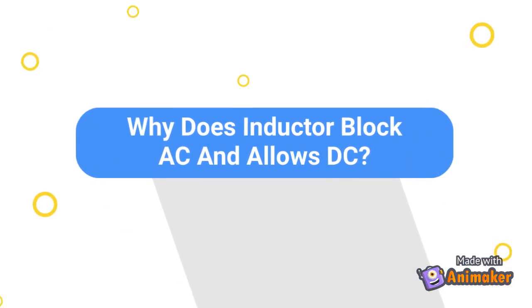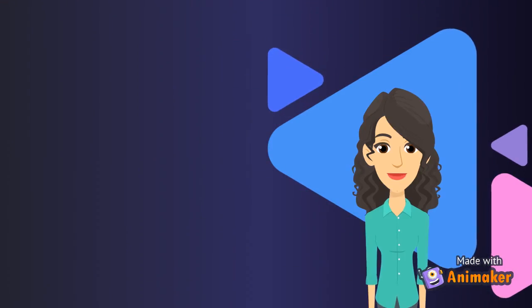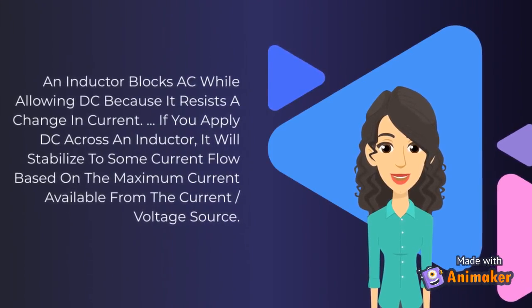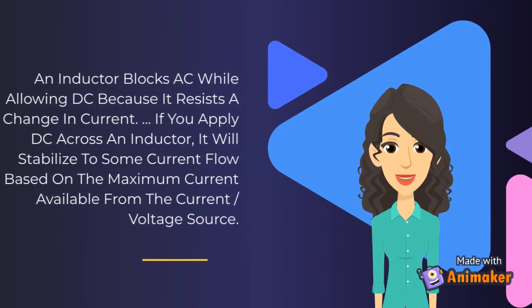Why does an inductor block AC and allow DC? An inductor blocks AC while allowing DC because it resists a change in current. If you apply DC across an inductor, it will stabilize to some current flow based on the maximum current available from the voltage source.